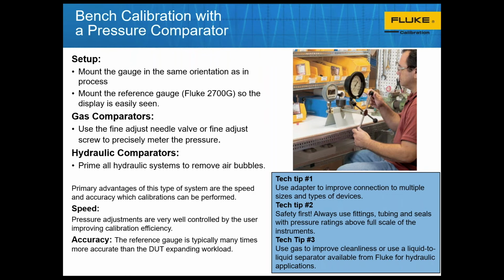If you have, say, gauges like this in the field, you could calibrate one, take it into the field, do a swap, bring the gauge back, do a calibration and put it on the shelf ready to go. It would require more equipment, but it would allow you to rotate your gauges and keep your process up and running and provide for calibrations in a bench type environment.